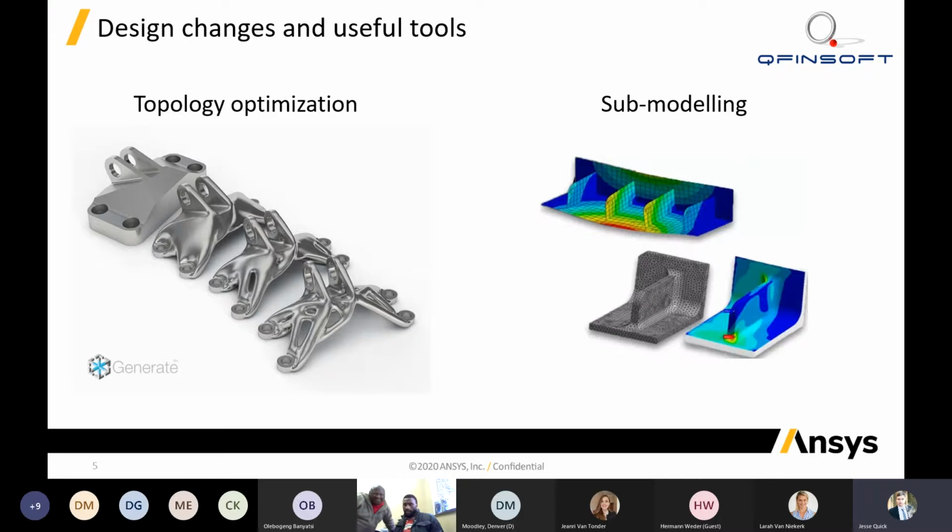So this is a tool that I often like to use. It's particularly useful if you're looking at welded geometry or an area of high stress concentration or any sort of area of interest. We take advantage of our computational speed with a very coarse model and then we refine it to a fine model. So that's effectively what we are doing.